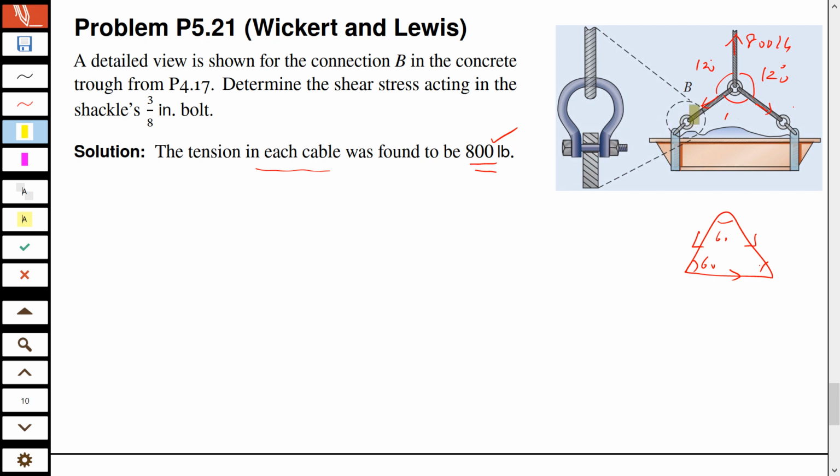So if you zoom this, now you understand what is, we didn't discuss it then. At that time, it was a question of statics, yeah? उस टाइम पे ये मटेरियल हम नहीं पढ़ रहे थे, we were not worried about how this thing is supporting it. लेकिन now you zoom it and now you see, oh okay, it is this bolt which is actually doing the job, yeah? तो यहाँ पे nuts हैं, एक bolt है, और it turns out that this is actually a problem of shear stress, ठीक है, क्योंकि this, although it's a tensile stress for the cable, but for this bolt it's shear stress, agreed? Because this cable is going to break this, it's trying to break or cut this